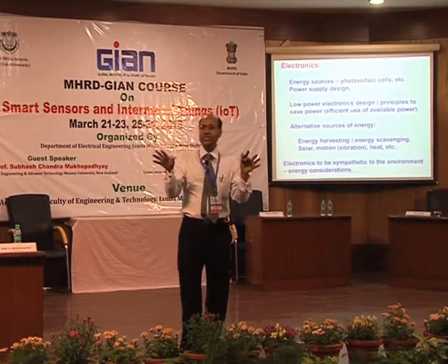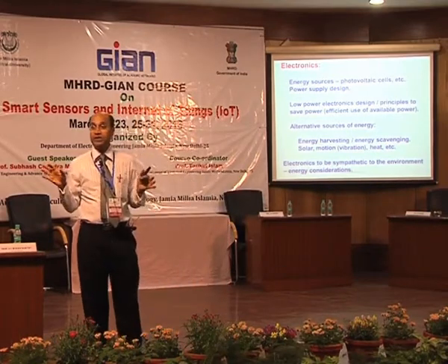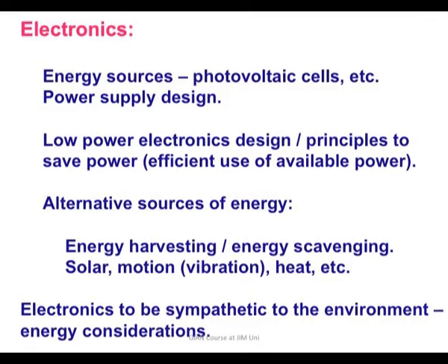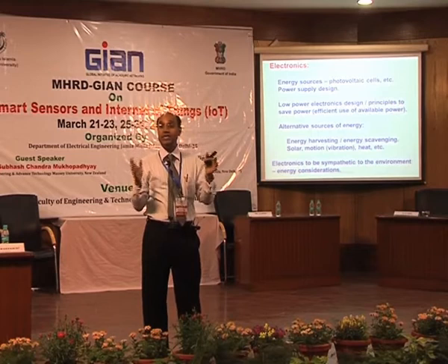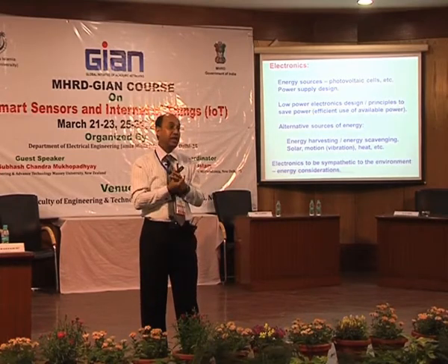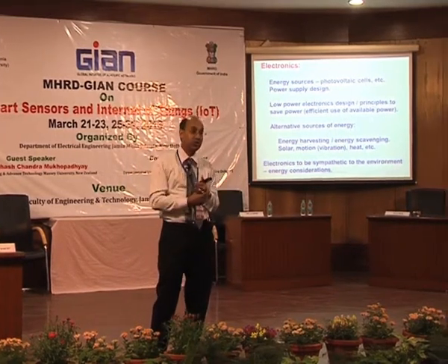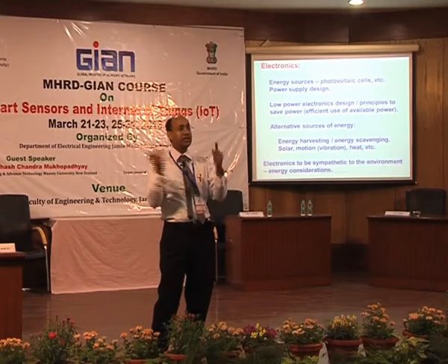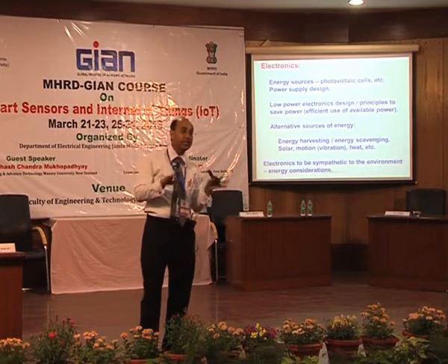So you need only 6-7 milliwatts for normal operation. But when it receives data and when it sends data, it takes around 40 to 50 milliamperes of current. So you need around 150 to 170 milliwatts of power for transmission and receive. And that's the amount of power you still don't get from other sources of energy. So research is still going on. We may have something in the near future, but at the moment we are really stuck.